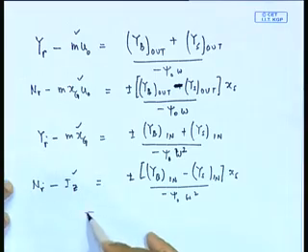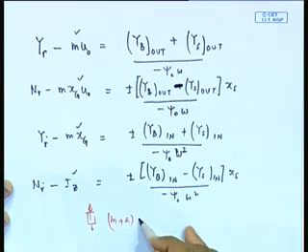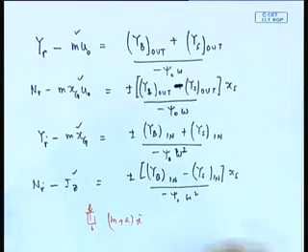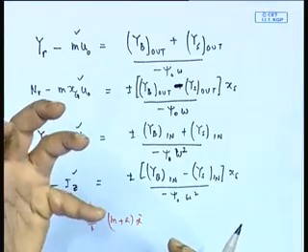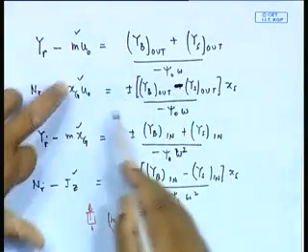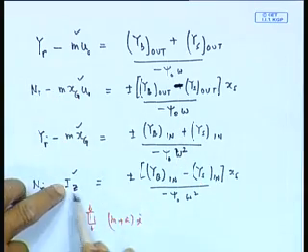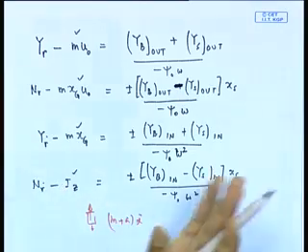For example, if I took a body and I oscillated it in water, I will end up getting mass plus added mass into acceleration force. I will not find out only added mass into acceleration. If I took a body in water and I accelerate it, my equipment will measure mass plus added mass into acceleration, that force, not only added mass into acceleration force. So, the measurement of yb out, etc. includes these parts, that is m u 0 into velocity, m x g u 0 into velocity, m x g into acceleration, and m x g into acceleration, Iz into acceleration. This one is very easy, Iz into acceleration, this is my inertia force.